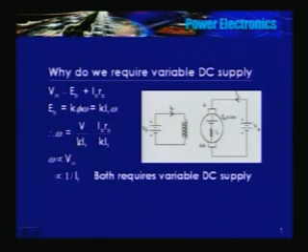Therefore omega is given by V in, the input voltage to the armature. The input voltage to the armature is not the input voltage to the motor; if I connect a resistor in series, that is not V in. V in is the voltage applied to the armature terminals AA. So omega equals V in divided by K IF minus IaRa divided by K IF.